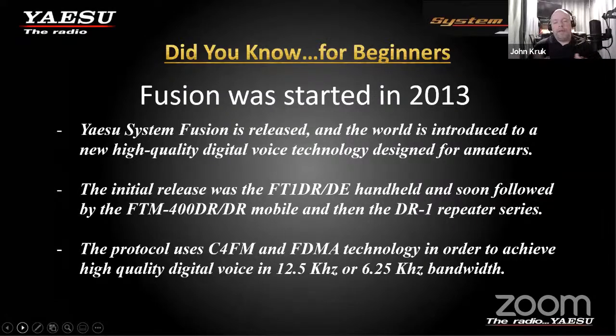Now, a lot of people have always questioned, why do we use C4FM? Why do we use FDMA? Well, we use C4FM because C4FM was being proven for usage in other critical digital voice environments. And primarily the one you're going to think of, and a lot of people do, is APCO 25, which is a standard created for public safety usage. That uses C4FM. APCO 25 created the format protocol.